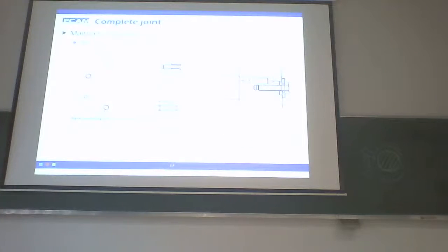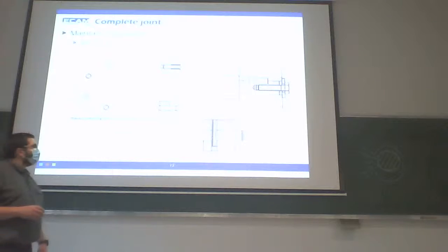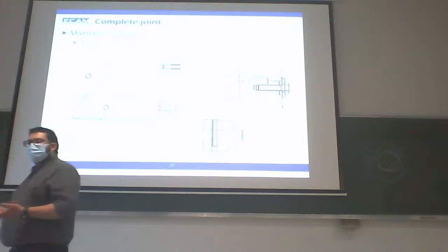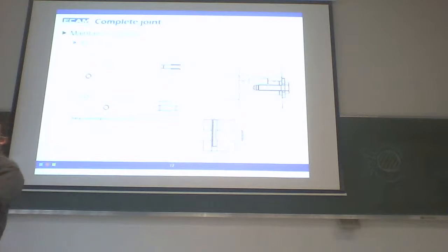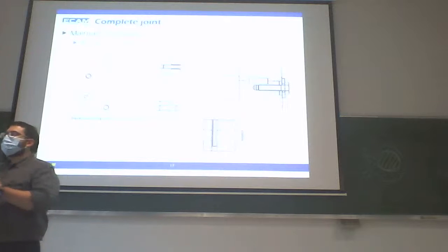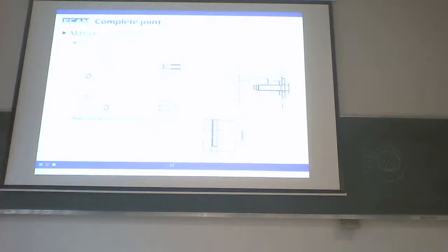It's sometimes possible to realize relative position and maintaining position in only one movement, with only one part. It's when you use an elastic pin. Here we'll directly stop all the movement. We have a cylindrical contact. The pin in the middle will stop rotation and translation. And because it's an elastic pin, the effort of the pin is sufficient to maintain position with support.